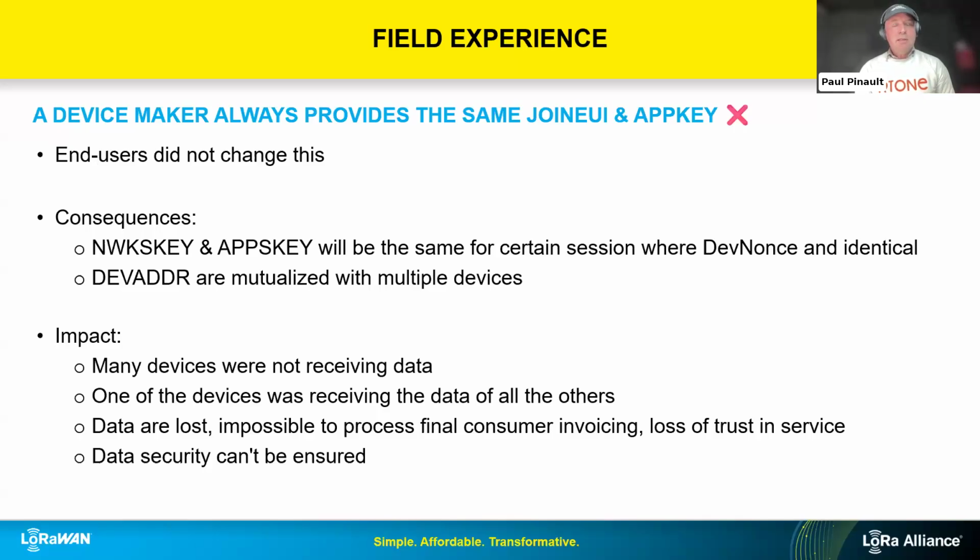And it's interesting because if you have a fleet of 1 million devices, you don't need 1 million DevAddrs. My experience is that we can use one address for something like 200 up to 500 devices sometimes. I recommend a maximum of 200, but it means that if you have, I don't know, 2 million devices, you just need around 10,000 addresses, which is reasonable, I would say.